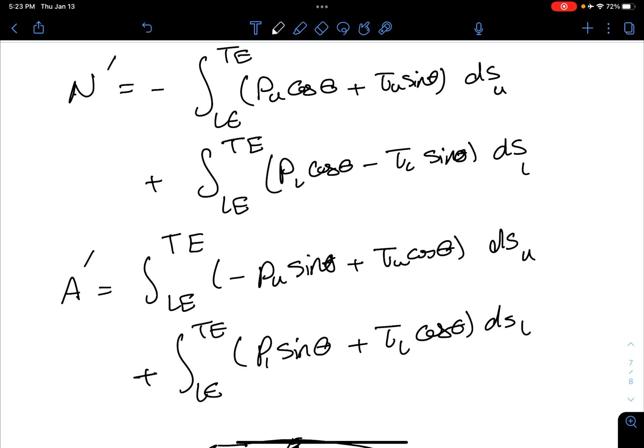Whenever you see double prime, when it relates to forces, we are talking about the force per unit area. Whenever you see just single prime, it's force per unit length. So double prime is talking about the force that is acting on a point, right? Single prime, a force that is acting on a line, like an airfoil, a two-dimensional thing. And no prime is talking about the force that is acting on a plane. Okay? Does this make sense?